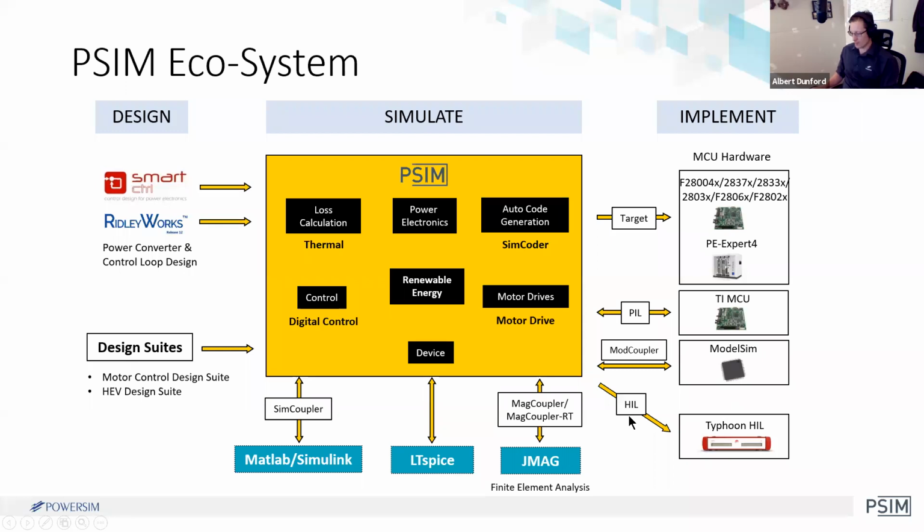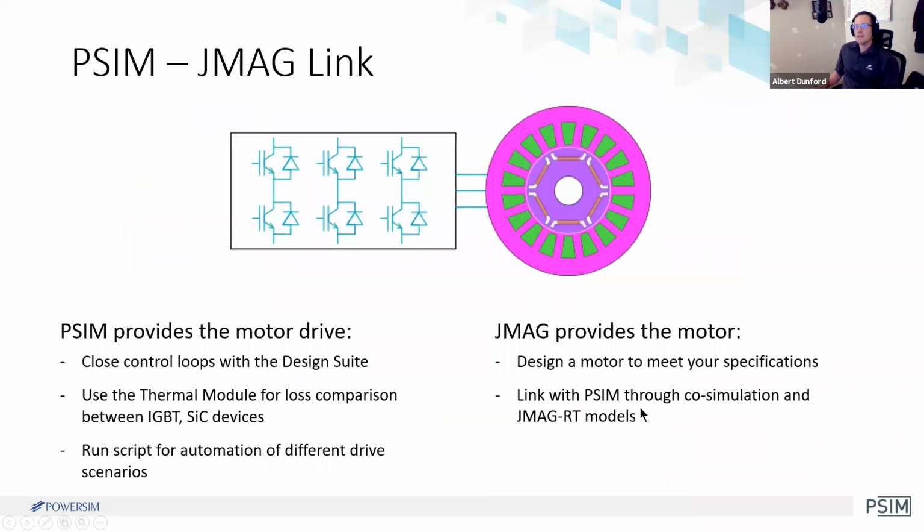But let's focus on the motor drive things for now. So the PSIM JMAG link. Essentially it's probably what you're expecting right now. PSIM provides the power stage and then JMAG provides the motor. So when it comes to the power stage in PSIM, we're talking about switches, either ideal switches or thermal device